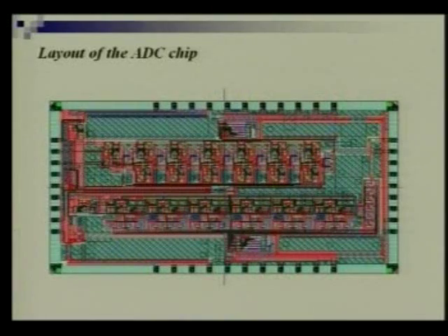See, here also you can see that this part is all back end. This part is being taken care of. These are being done by the metal to take care of the stability, so that the chip doesn't get twisted. So that's the way the layout is to be done. So these are the final circuit, and this layout with the bonding pads, you can really go ahead.